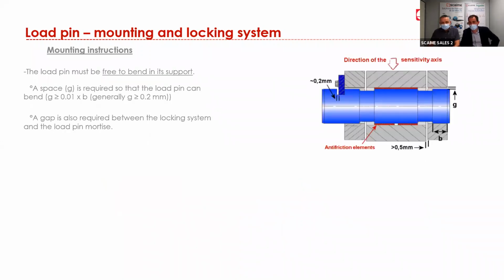About the mounting instructions, as we saw before, a load pin needs to bend in order to measure the force applied. So it is very, very important that in your system you define spaces in order to let the load pin bend in its support. As you can see from this drawing, there are mainly two gaps that need to be defined.